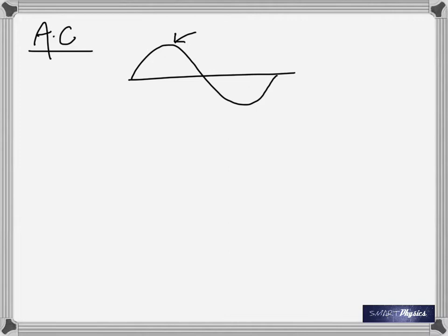But you can also say this is a DC source, a source of direct current. Why? Because if you connect a resistance to this, we know that the current is always going to flow in one direction, isn't it? Current always flows from positive to negative. The magnitude of the current is the same, the direction is the same. For example, if this is 5 volt and this is 5 ohm, what's the current? 5 volt and 5 ohm, what's the current? 1 amp. Thanks. 1 ampere. Is that current going to change? No, it's constant in magnitude. Is the direction going to change? No. That's why it's called a direct current.